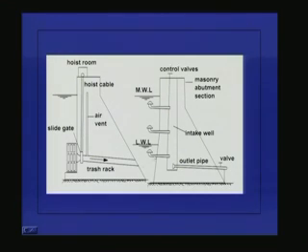Again, we can also have another type of intake for gravity dams, to take the water from the reservoir behind a gravity dam. Here in this figure A, there is only one port of entry, and that is kept at the bottom of the reservoir. Here we have multiple entries: one entry below the low water level, one at the middle, and another below the high water level or maximum water level, and this water enters into this intake well. This is the intake well that I am showing.